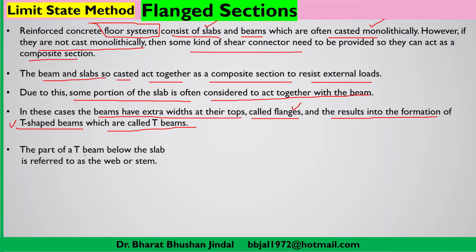And the part of the T-beam below the slab is referred to as web or stem, and the component of the slab which is acting as the component part of the T-beam will be called flange. So that means a T-beam consists of flange at the top, and below the flange, that is below the slab, the portion of the beam will be considered as a web, or you can call it a stem.